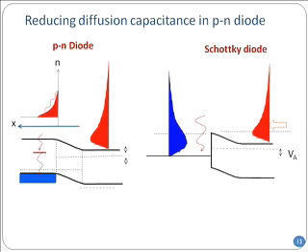Now, you could make the PN junction diode almost as fast as the Schottky barrier if you do this. Many times people will intentionally put in defects on the minority carrier side. If you do that, then as soon as the minority carriers go there, the defects will provide a sort of byway or a shortcut to join the majority carriers. And if it can join the majority carrier first, then the amount of stored diffusion charge on the minority carrier side is very small, and as a result, this could respond as fast.